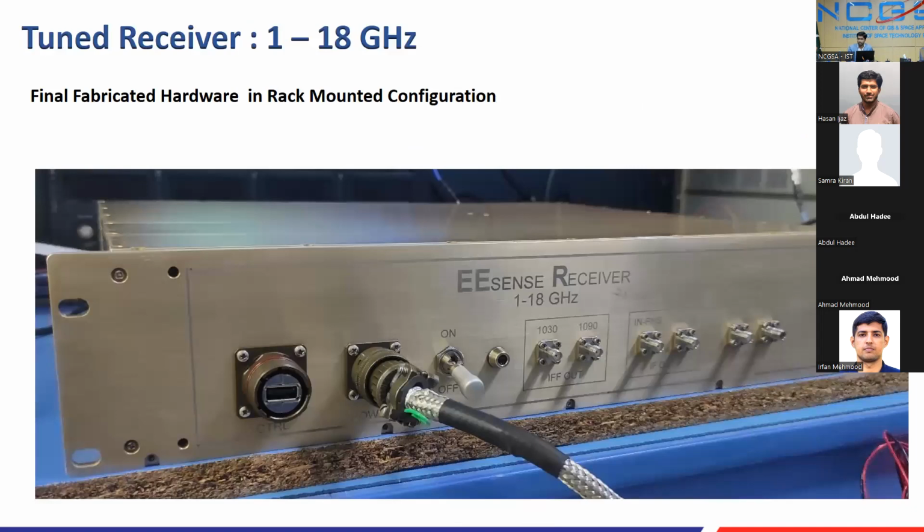It's in trials with the customer at present. It has a very good response. 1 to 18 gigahertz input. The customer requirement was input 1 to 8, so we used a solid state or a mechanical switch at the back, merged the inputs to 1 to 18, and then sent it on, because whatever the customer says, you have to do this. Okay? So this was our first product from my team.